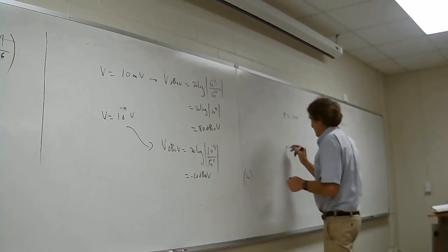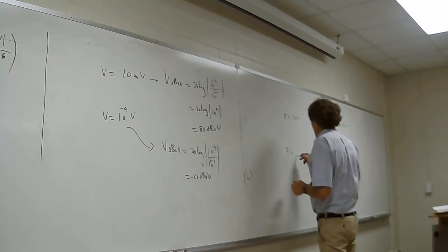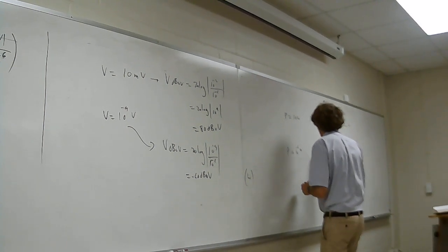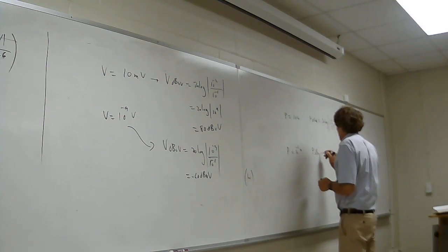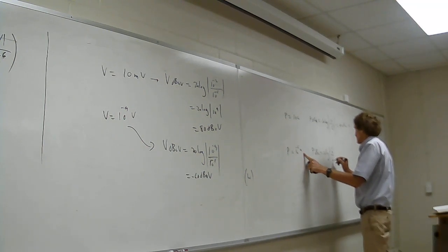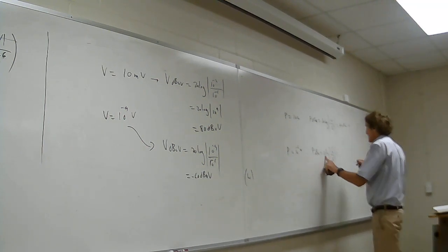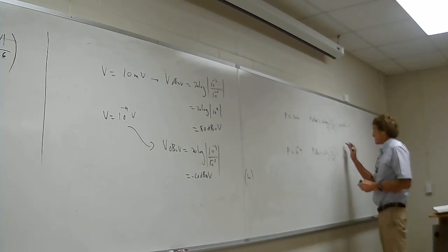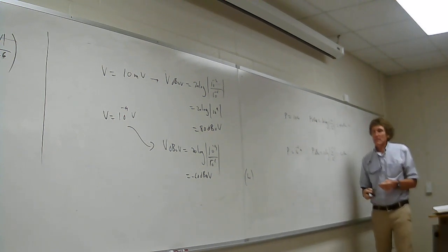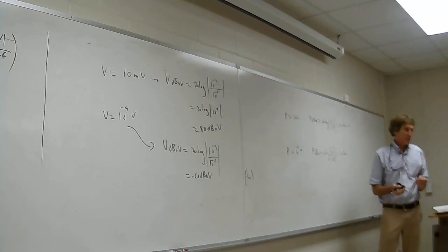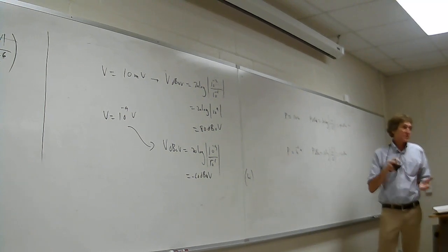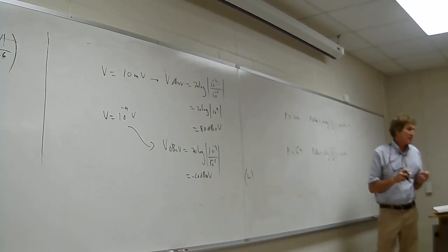Now, what happens if I have a power of, say, 1 microwatt, or 10 to the minus 6 watts? Now what's the power in dBm? 10 times the log of the magnitude of 10 to the minus 6 over 10 to the minus third, right? That's 10 to the minus third, so that's going to be minus 30 dBm. And again, I'm going over how many? 7 orders of magnitude there. Y'all agree with that? And you can see I go from minus 30 to 40 dBm, which is a very compressed range, and that's the reason we use dB.